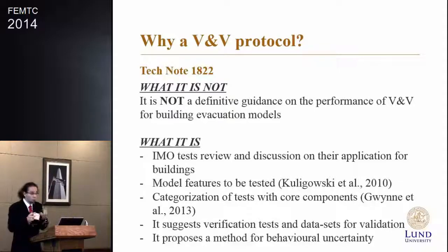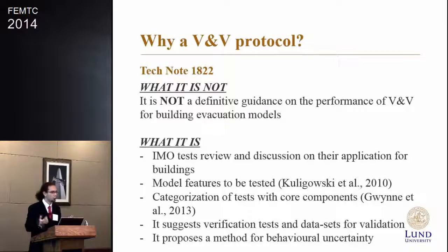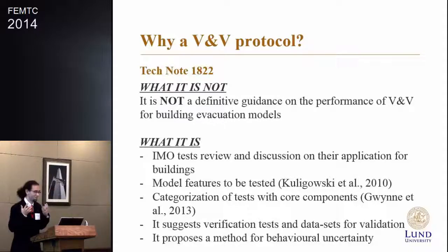And then after reviewing the IMO tests, we gave some suggestions on what can be possible verification tests. Of course, there are many ongoing debates within the evacuation modeling community: what are the features that should be tested, and in which way they should be tested. But we gave our point of view as researchers that is completely unbiased. We don't have any reason why we should say this should be included in the model, this should not be included. And it depends on the field of application, because as I said before, the main problem with the IMO tests is that they are specifically designed for maritime applications, and they're used also for building applications.